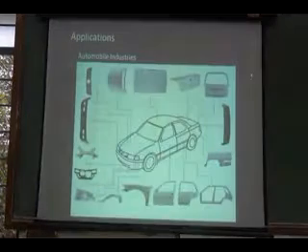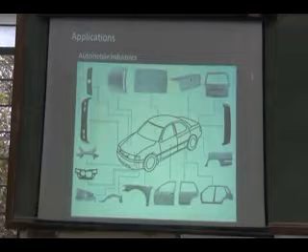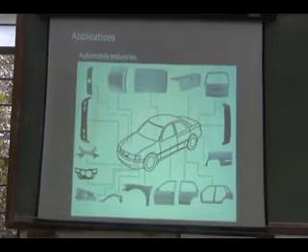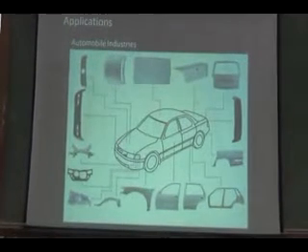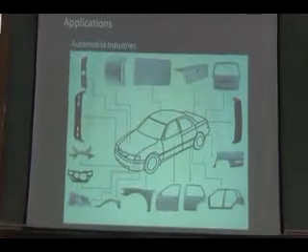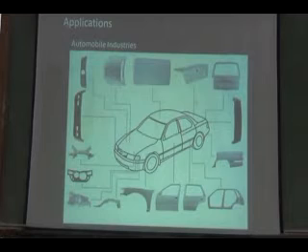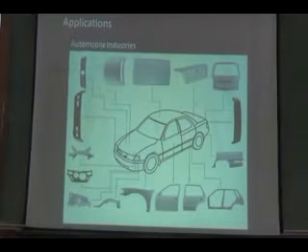Go to the next one. So where is it applied? Application, make a note, applications. In the automobile industry, we need an exact sheet to be used, right? If we know the development of that portion of the sheet metal component on the surface of the car, then that exact material alone will be used and it will be pressed into the shape we need. So to avoid material wastage in the automobile industry, the body is developed using development of surfaces. Then it is formed into the required shape.